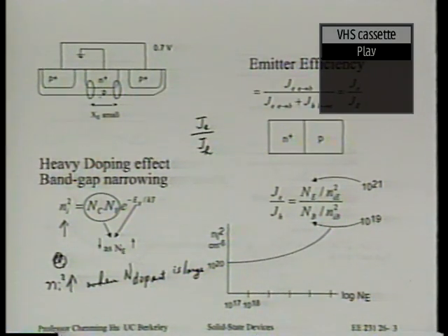For example, what are the things to trade off between the gain and the cutoff frequency? If I wanted to push the gain of a silicon germanium transistor higher, I'd simply use a lower dopant concentration in the base. You see that? But that's going to introduce series resistance in the base and kill my cutoff frequency. So what do I like better? So it's usually this kind of trade-off. I just want good enough gain and everything else is thrown into speed. That's why you don't see significantly better gain.